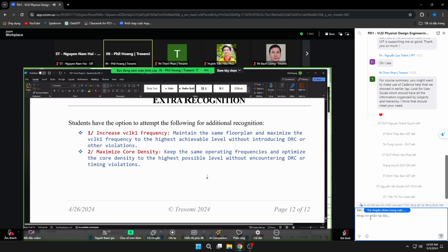So you start shrinking the core, and you find it's pad limited, meaning you can shrink the core, but the space from the core to the IO might increase from 100 to more, because you cannot shrink the IO anymore. But you can do it, so at the end you might have the same speed but a smaller design. Those are the actual candidates.